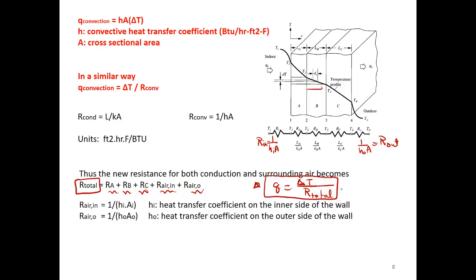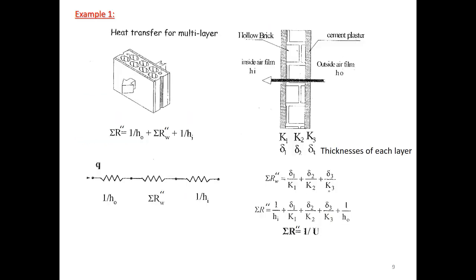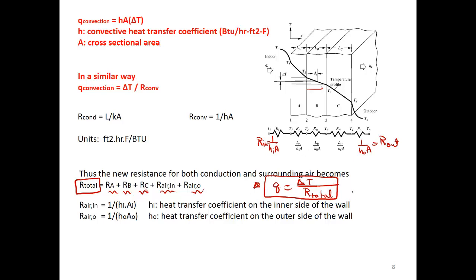And that's what we use for the definition when we say UA delta T. So U, as you see here, UA is equal to 1 over the total thermal resistance. So if the thermal resistance increases, so you have more resistance, then U decreases, right? So U is actually 1 over RA. If you want, A is just a constant.